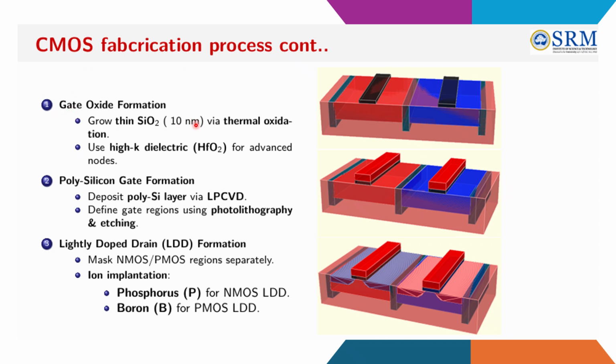In order to develop the gate, you should undergo the thermal oxidation process, that is called oxide formation. So again, how will you do it? Exactly with the help of thermal, that is high temperature, you are going to develop Si plus O2, that is SiO2. Here it will grow at high temperature. Now definitely you have to use the polysilicon layer over this gate.